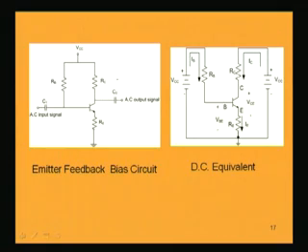In this circuit also, if we consider the DC equivalent circuit only, that means when DC conditions prevail, there will be open circuits at these two points because of the capacitors C1 and C2. So, we will be left with this DC circuit without these capacitors, and again I am separating out these two VCC sources just for easy understanding, nothing else than that, and then I can analyze the circuit separately.